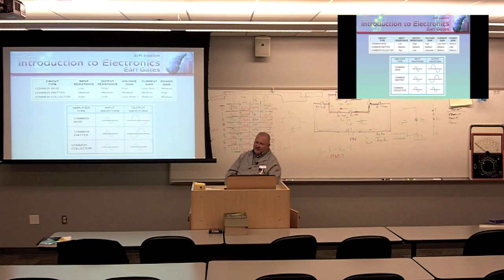If I have a high impedance microphone, and maximum power transfer takes place when the internal impedance of the source closely matches the internal impedance of the load, which configuration would I want to use? High to high. Common collector. So an engineer designing the first stage of that circuit would probably choose a common collector configuration to closely match the impedance of the microphone.